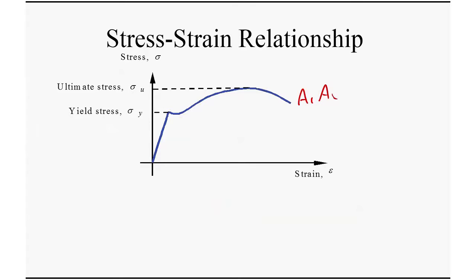And in the small deformation range here, within this range, we see this portion is very linear, right? So it's a linear part, and we like this part. It's a small deformation. It's easier, linear, right? Linear equation. So stress is proportional to strain in this range. And in this class, we always talk about this range. We do not talk about the nonlinear plastic range, right? Okay, so in the range we are considering, the small deformation, small load range.